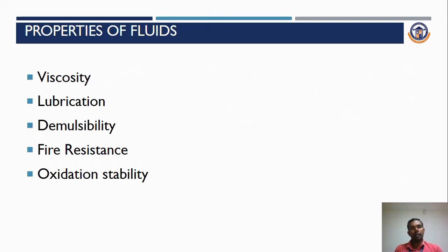What happens in a hydraulic system is that fluid flow resistance occurs. Similarly, when viscosity decreases, temperature increases. Due to the decrease of viscosity, internal fluid leakage happens in that hydraulic system. Lubrication reduces friction, and the main purpose of lubrication is to protect the internal parts of the hydraulic system from any damage or wear.